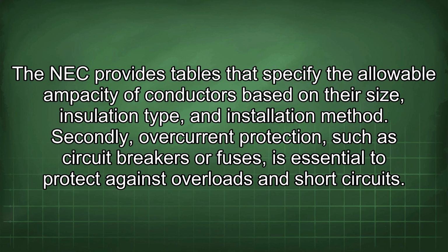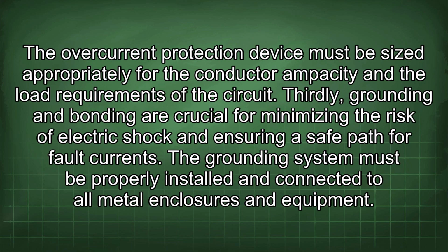Secondly, overcurrent protection, such as circuit breakers or fuses, is essential to protect against overloads and short circuits. The overcurrent protection device must be sized appropriately for the conductor ampacity and the load requirements of the circuit.